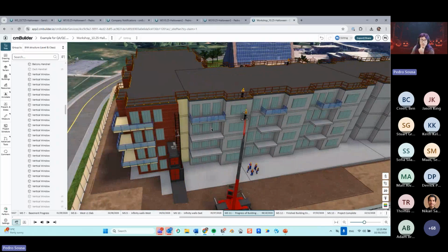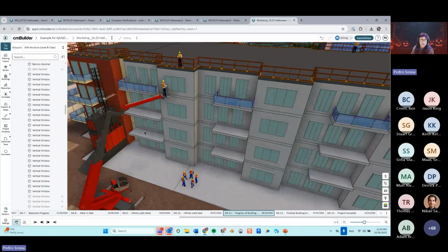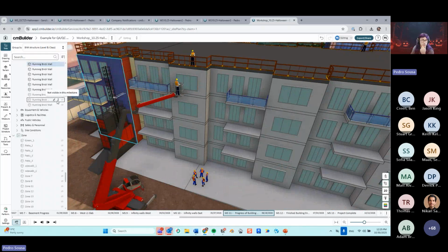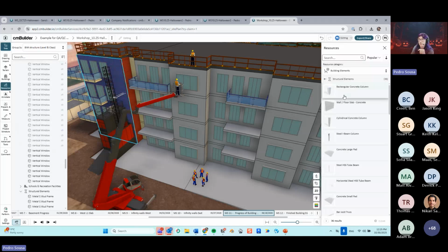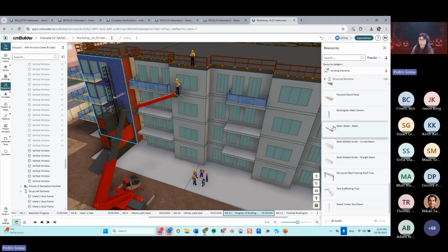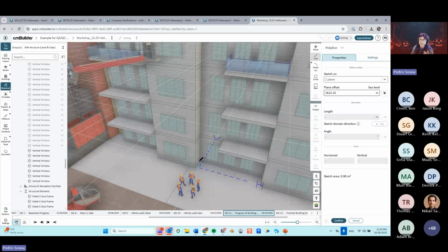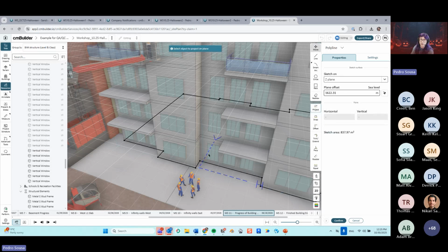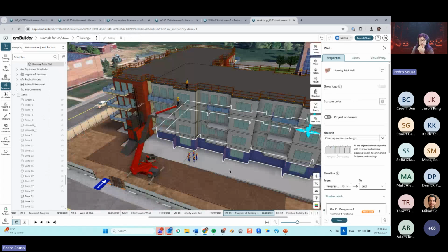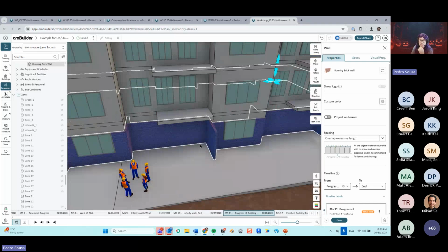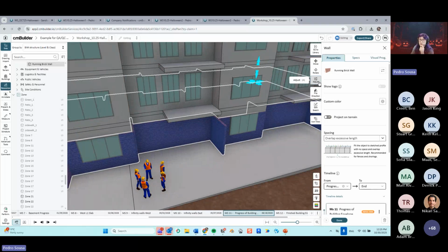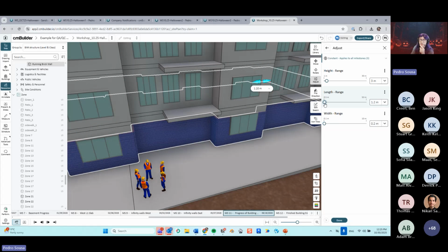Okay, and for the textures here, you would use the brick wall resource, right? So the running brick wall resource, you can put that as either a line or a point. As a line, you can simply project the elements like the whole facade panel over here, and then for these areas that are sticking out a little bit, you can go into the adjust function and reduce the length of the wall, because this is happening because the minimum length of each wall panel that we're placing over there is defined by this parameter.